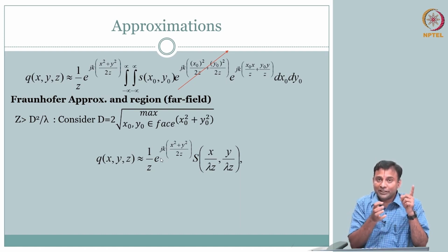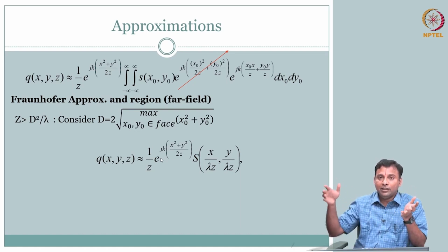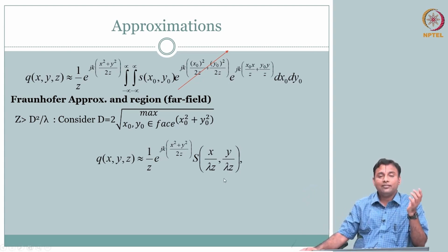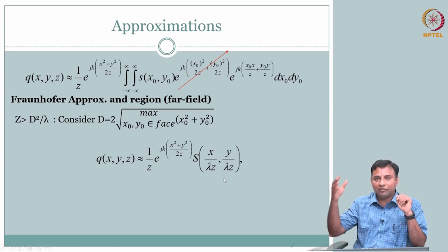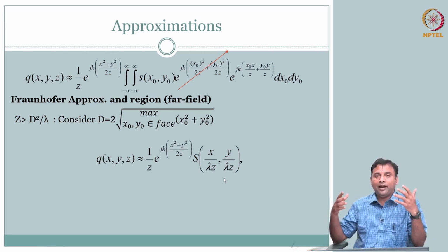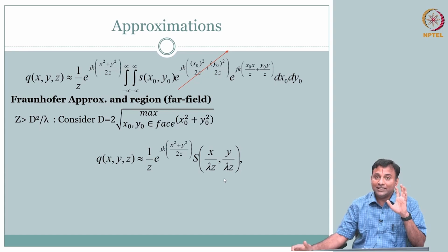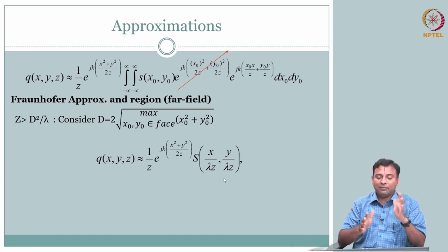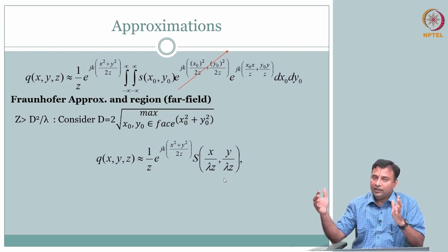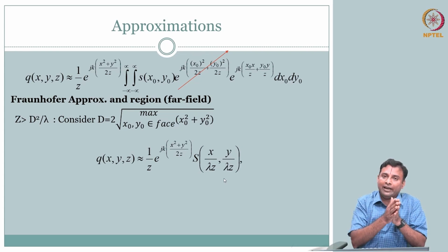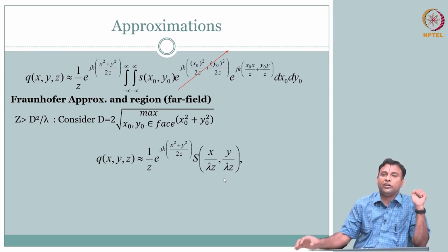The Fourier transform of the shape is going to give you the far field pattern, right? The pressure distribution in the far field, the shape of that, right? That pattern is mathematically described as the Fourier transform of this shape, and the size of this is also going to determine where this is applicable, whether you are in the near field or far field. So you see the size and shape of the transducer determines how this pressure is going out and where all you are getting the reflections from and the sum total that you are getting.